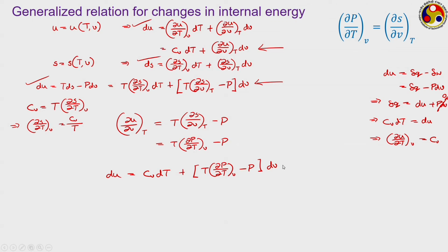So, what we have now, look at the left hand side, here we are talking about the changes in specific internal energy, whereas on the right hand side, we have specific heat at constant volume, Cv, and we only have temperature, pressure and specific volume. So, if we know the PVT relationship of any particular substance, something like an equation of state, ideal gas equation of state, etc., you can easily calculate the changes in internal energy using that knowledge and also the knowledge of this Cv.